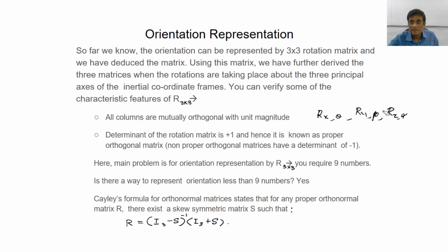So psi, phi and theta, followed by another rotation. So the body will ultimately, after undergoing 3 rotations, reach somewhere, right? And where it has reached, you can capture that orientation change simply by multiplying these matrices, but in order.